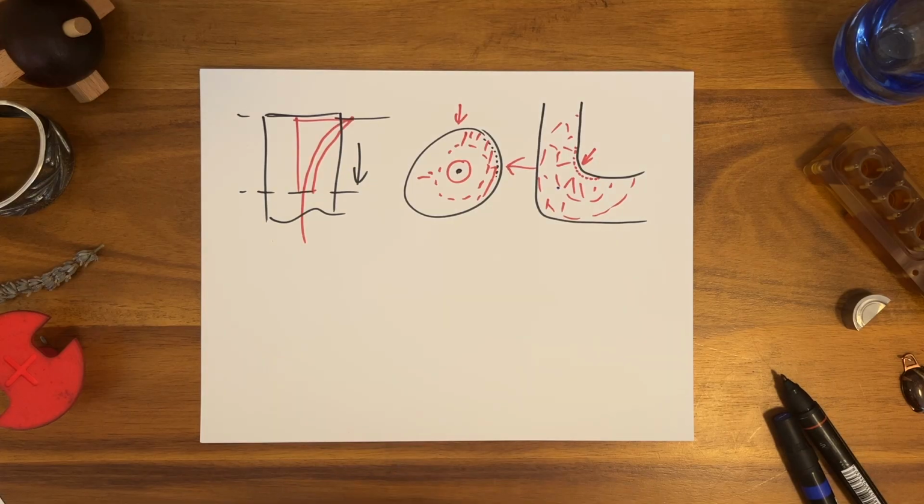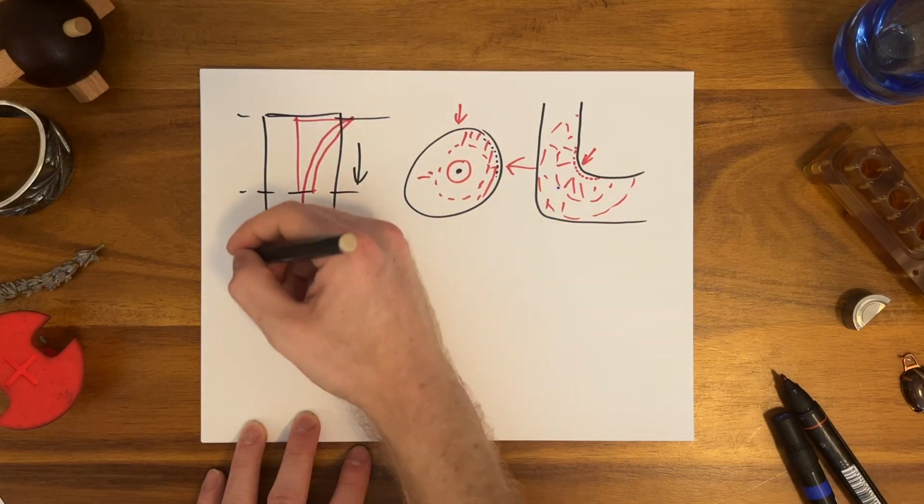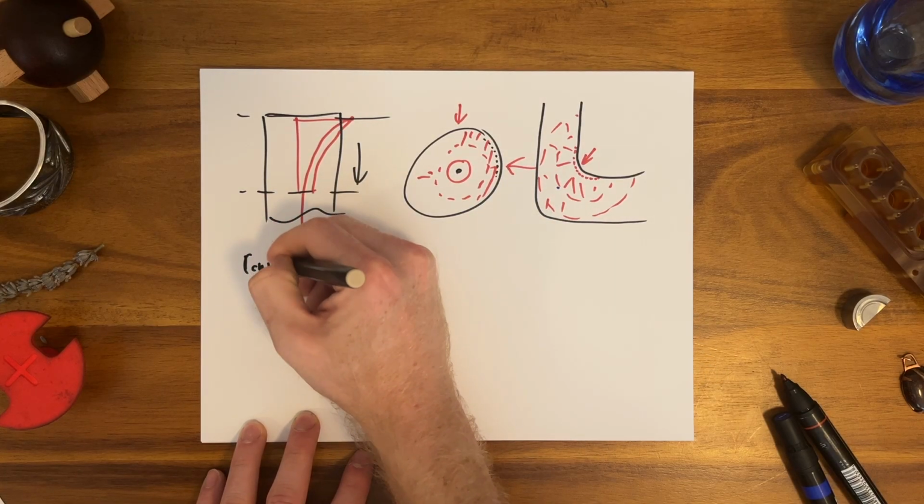The other thing is that the semi-infinite solid model makes a weird assumption on boundary condition. It assumes that the temperature of your boundary has suddenly changed from initial to final. That's pretty difficult to do. It's a really easy equation, but that's not quite accurate. There are two other boundary conditions you can do. You can do a convection boundary condition.